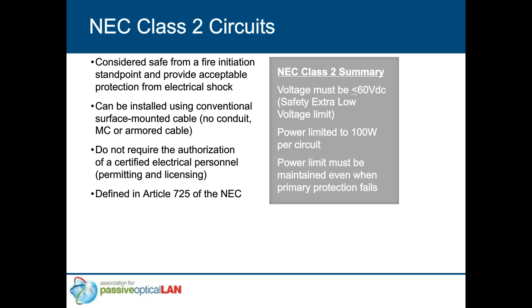Now, this is an important clause because it, in effect, eliminates the use of fuse panels in a Class 2 circuit. And here's why. With a fuse panel, which you're familiar with, you have a 48-volt input from a rectifier, and say you use a 2-amp fuse. You could argue that 48 volts times 2 amps is 96 watts, therefore I meet the standard.